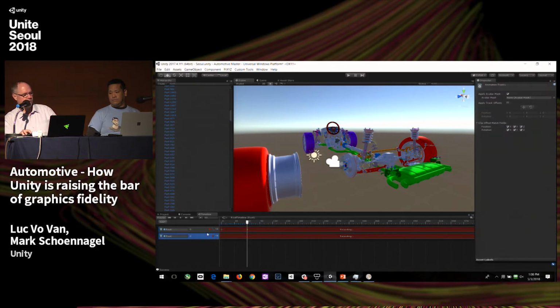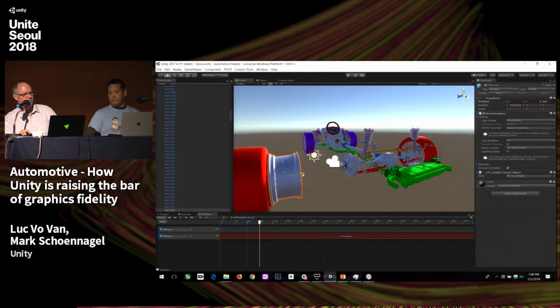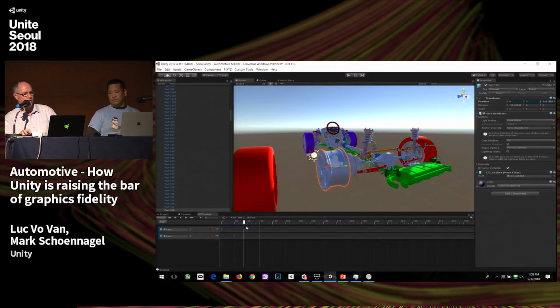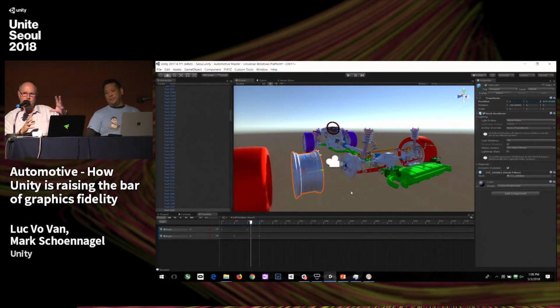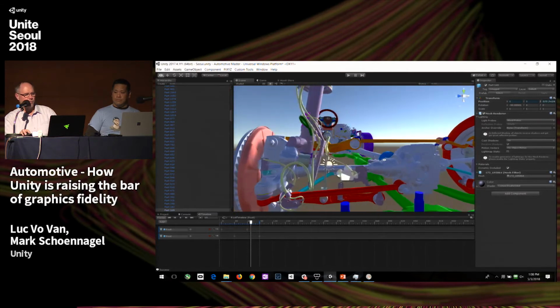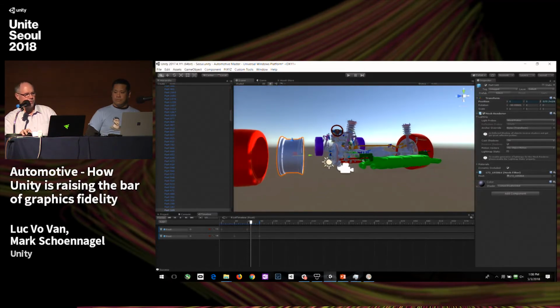Make sure you have the correct timeline selected. Go here to frame 90. Grab that. Give it a little nudge. That sets the keyframe. Go back to frame 30, 31, somewhere right there. Set this to 0. And just that easily, I've created the beginnings of an exploded view. So obviously, you could be very creative here. You can make these pieces go any way that you want. And then we could dive in, start to take a look at this brake assembly, and really get a good idea of how this was created.